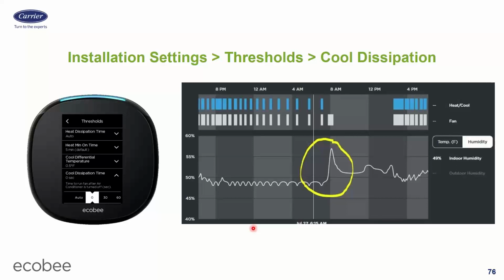If I continue running the fan, all that's going to do is help take the moisture that's sitting on the coil and blow it back into the airstream, evaporate it back into the airstream, instead of letting it drain down and go out the condensate. So I want to make sure the fan is off in this scenario. So switch it from auto to 0 for 100% of your projects, unless you do a project for a buddy that lives in like Arizona where it's like freaky dry or something like that. But everywhere else in the world, that's not a desert, make sure this is 0.